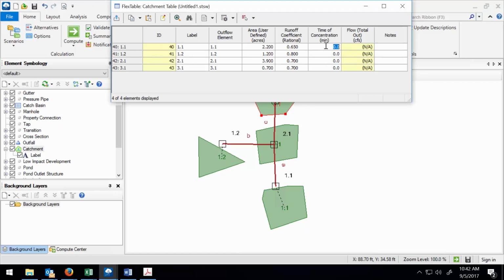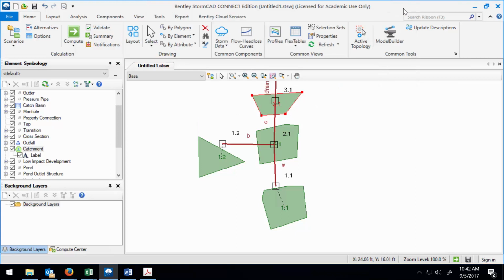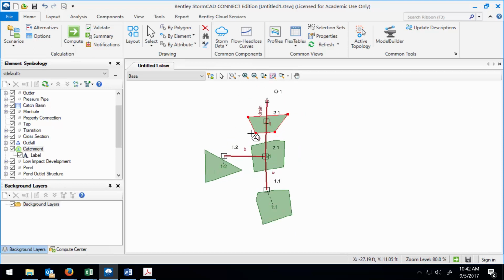Okay, so that first one is going to be 11 minutes. Then 1.2 was 9.2 minutes. 2.1, 13.7 minutes. Finally, 8.7 minutes. All right, so I've defined everything that I need to for the times of concentration. Let me zoom out a little bit, make sure that we've...